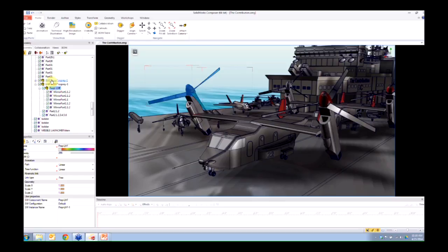So here I have, for instance, a sub-assembly of this unit here. I have another one of that unit there. Under that unit, I have the propeller. Under this one, I have the propeller. Now that makes things really easy, because now in the views, I can take this unit and rotate it, and then in the animation, rotate the propeller separately using the assembly selection mode, which again is under assembly, and I have it selected right there.